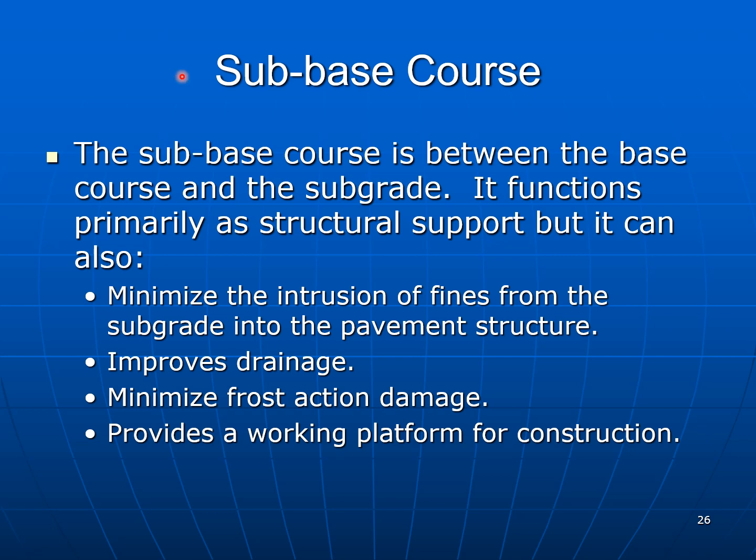Then comes the sub-base course. The sub-base course is between the base course and the subgrade. It functions primarily as structural support, but it can also minimize the intrusion of fines from the subgrade into the pavement structure, improve drainage, minimize cross-section damage, and provide a working platform for construction.